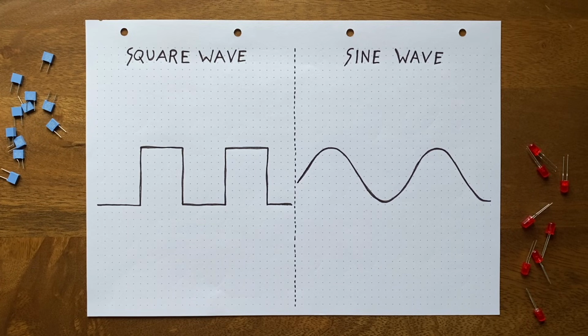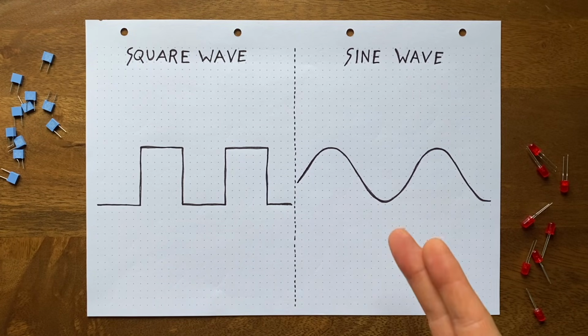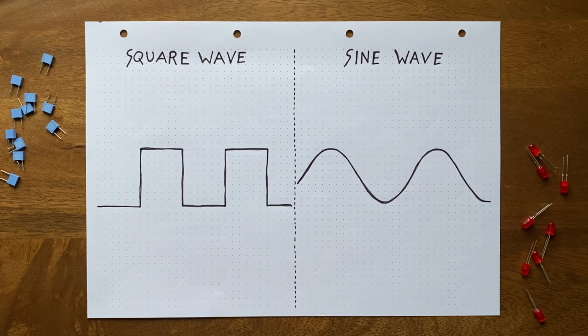Coincidentally, if we send our square wave through a low-pass filter, the result will actually look and sound a lot like our sine wave here. If that's the case, and you'll need to take my word for it for now, then we can make a rough assumption about which trait gives a waveform its high-frequency content. Because if we overlay our square and our sine wave, we can clearly identify what sets them apart.